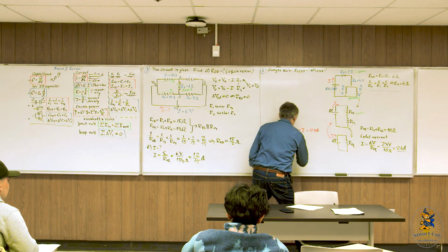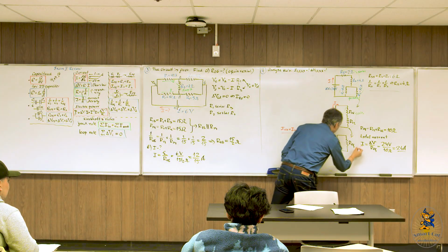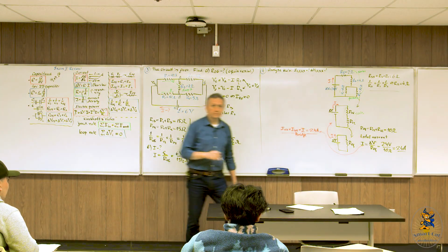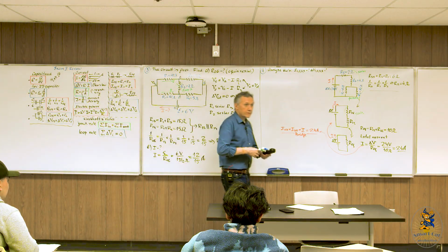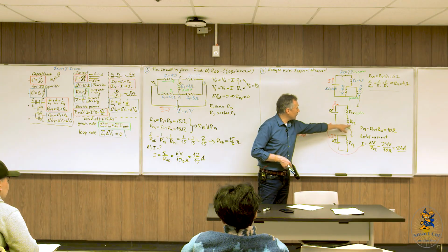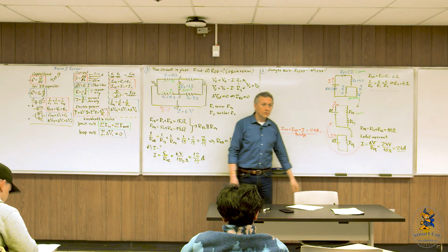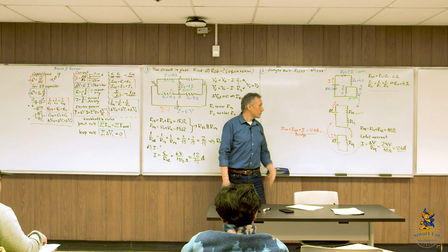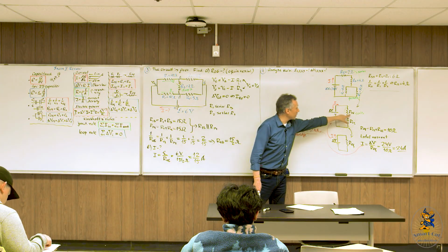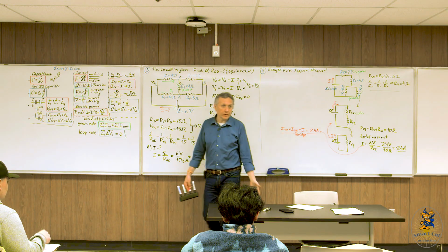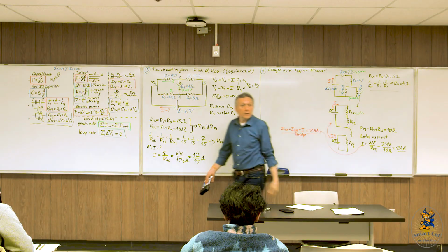So that's what I usually call a bridge. And again, this current comes from there. Okay, so now that we have this bridge, what can we find through these resistors? Okay, my question was not about current, but voltage, of course. Now we know the current through this and the current through that. We found the resistances R35 and R12, so now we should be able to find the potential differences.